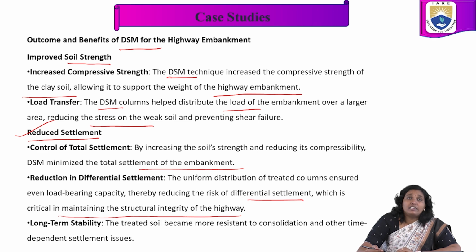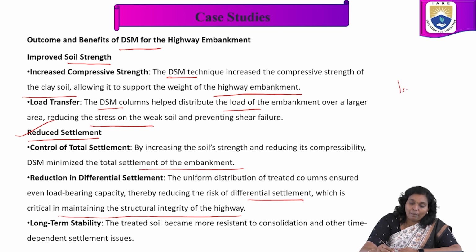This reduction in differential settlement is very helpful and one of the major benefits of deep soil mixing in highway abutments, because the uniform distribution of treated columns ensured even load bearing capacity.